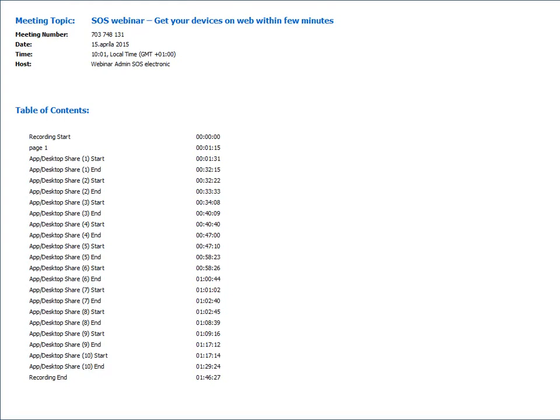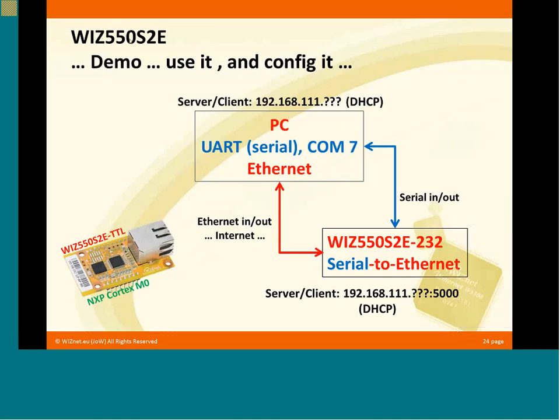Share my PowerPoint again. I had one more question we have. Yeah. Okay, so the other question is, can I use the VSNet configuration tool for the VSP210 module? Oh yes, but it's a different configuration tool. It looks very similar. So it's the same. You set up the serial setup side and you set up the Wi-Fi side. There is a configuration tool for the 210-220 Wi-Fi module.